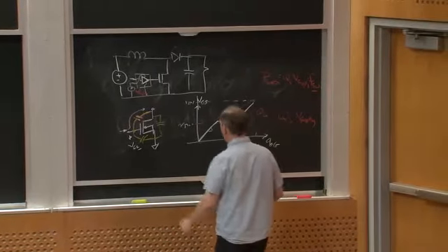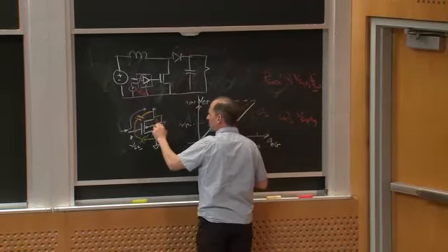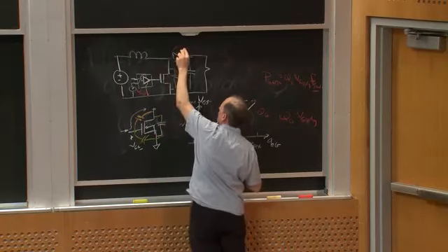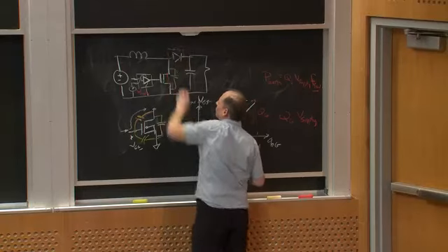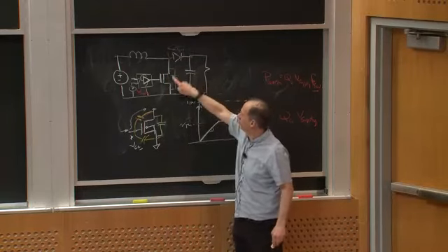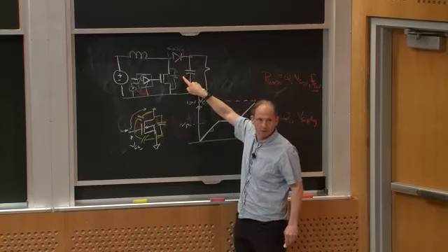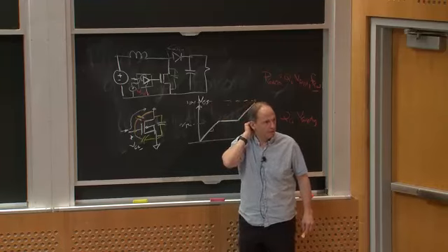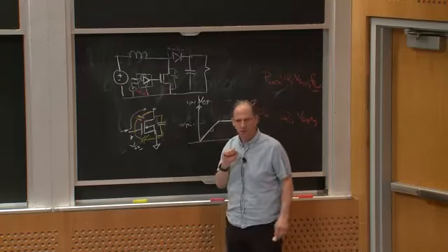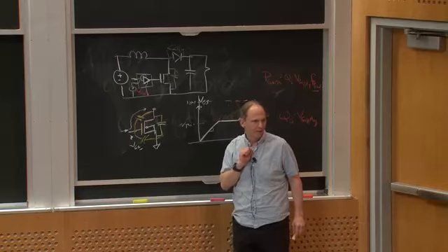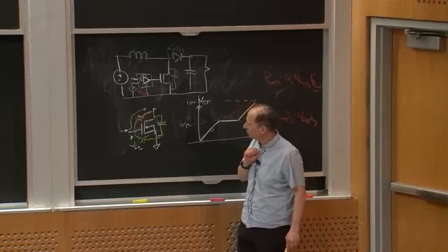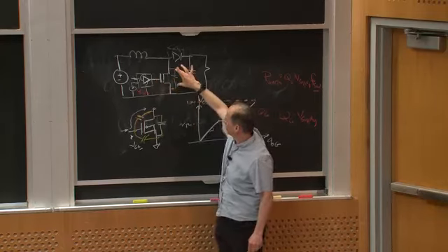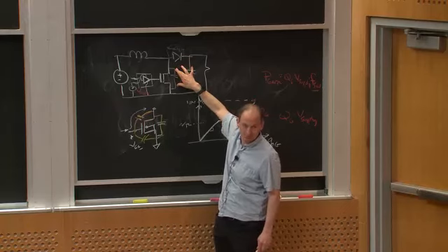When I turn this transistor on, I'm discharging this capacitance, right? So I have some capacitance here, and I'm discharging it into the switch. Capacitance on my diode, I'm charging it into the switch. That causes a huge pulse of current in this loop, which could cause a lot of noise if it rings a lot, right? And yet, the amount I lose, at least in the capacitive portion, doesn't depend on how fast I turn it on, right? So at some level, maybe I'm motivated to turn on my switch somewhat slowly so that I don't discharge this capacitance really, really fast and cause a lot of noise.